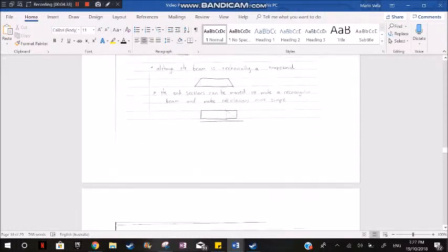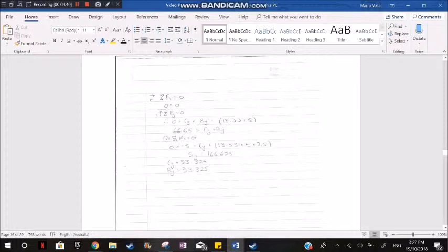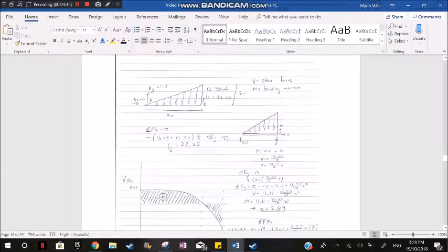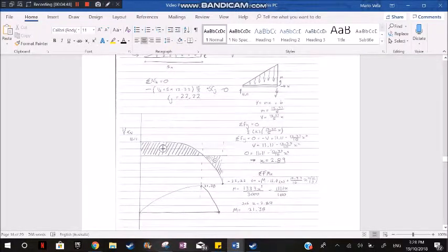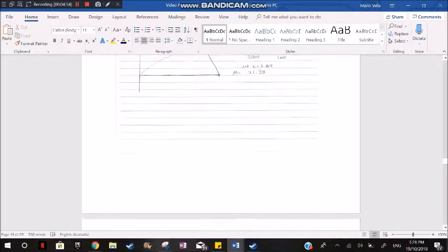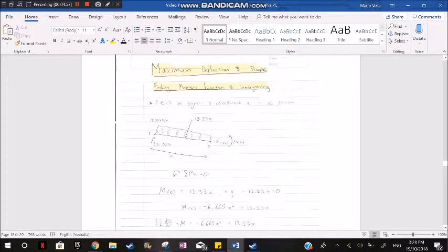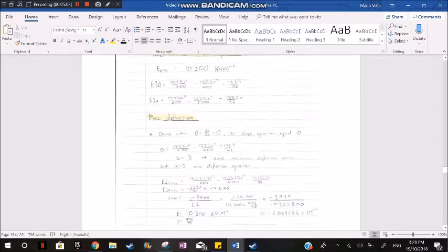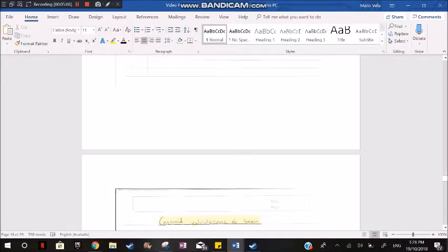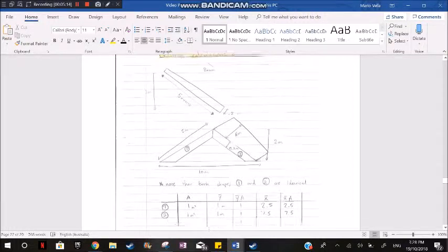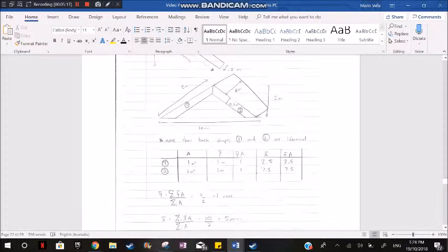That's my force equations, just to find the moment equation. This was my old shear force and bending moment diagrams, but I did change these up a bit to make it more simple. Maximum deflection and slope, I've already spoken about these. Same thing, boundary conditions, max deflection, maximum slope. Then the centroid calculations of beam, as you can see here, that's a singular beam I was working on, but now I put them together I've got my width and everything, my calculations. I've kept it 2D.